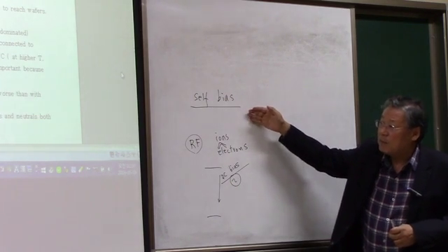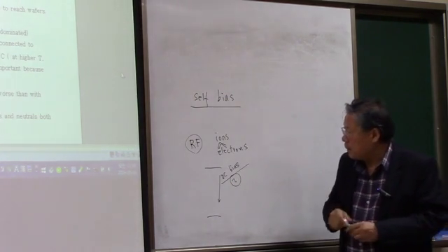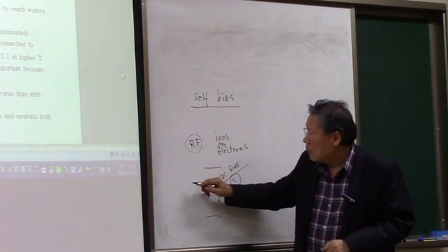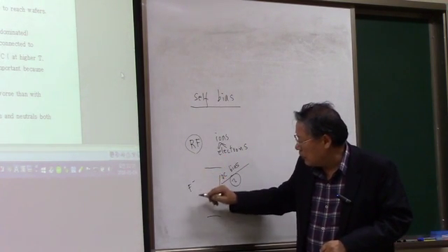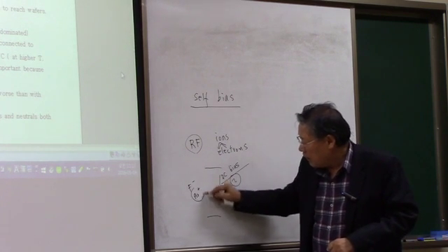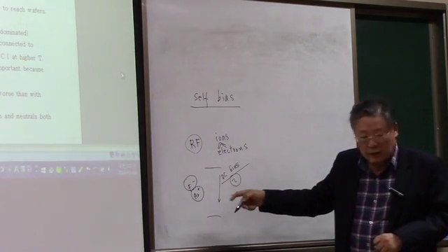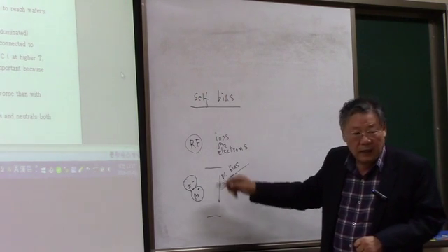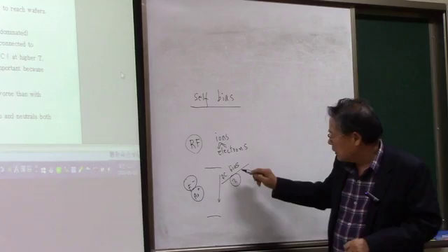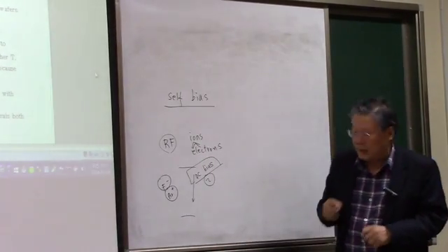So because of this DC bias, we form a self-bias. With this self-bias, the ions, for example, the fluorine ions or argon ions, whatever, are going to be accelerated with this DC bias, okay?